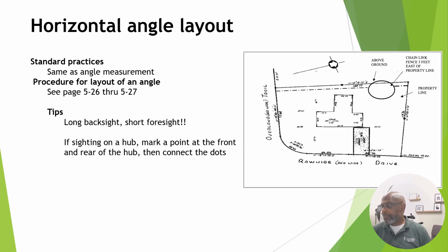Even if the points have been marked clearly, it is possible for someone to inadvertently get on the wrong point and give a line to a backsite, or perhaps numerous targets have been established around the site, and it could be easy to sight into the wrong target. Always perform an additional check to ensure that the correct point is used as a backsite for the angle to be turned.